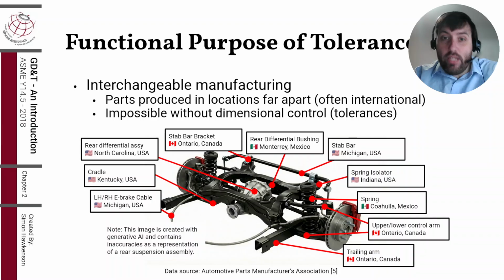If one singular part has its tolerances off, problems will show up in assembly and it'll often halt that assembly line. The problematic parts often have to be scrapped and replaced with new ones. This is all very expensive. It's usually cheapest to make sure that your parts are toleranced correctly at the design stage and inspected before being sent to assembly.